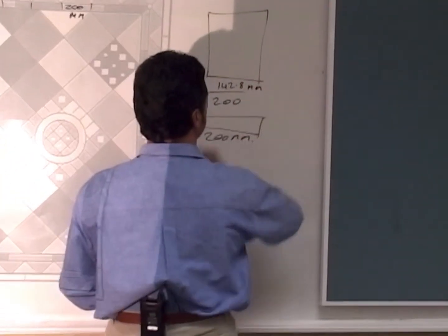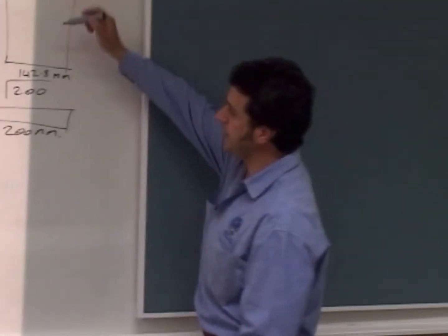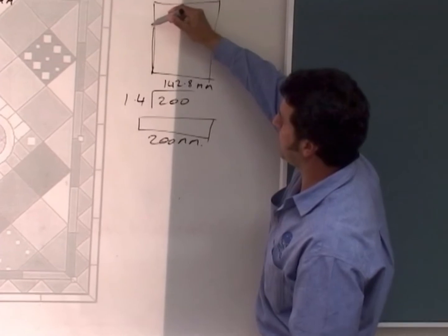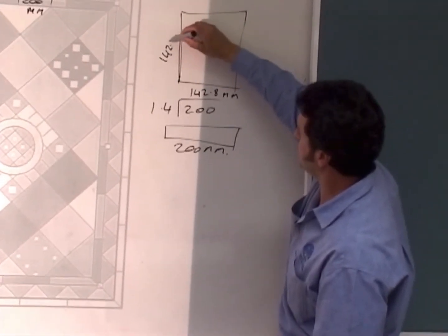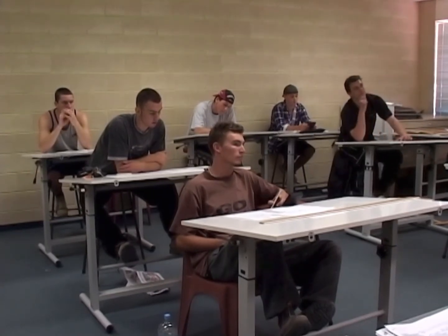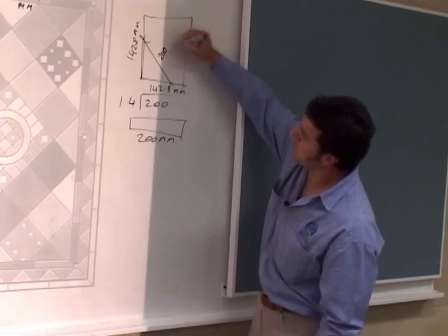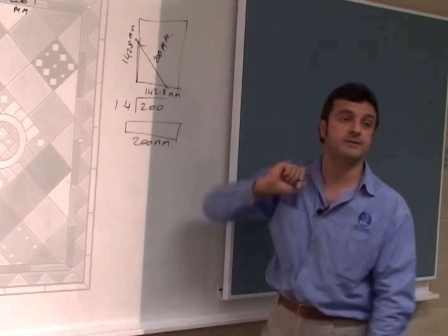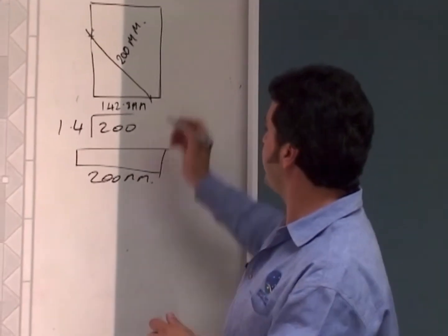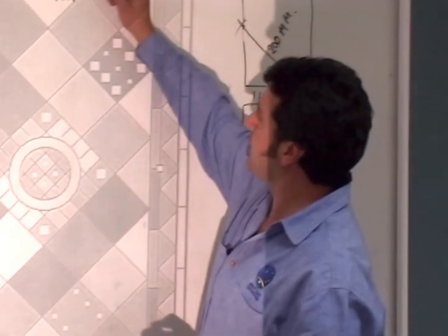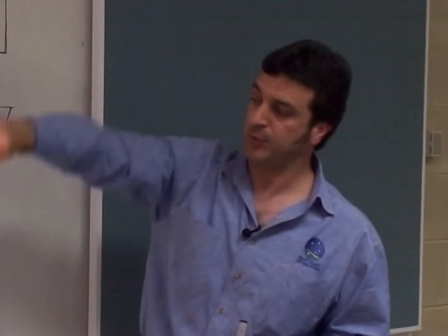So we've got 142.8 millimetres. That tells us that if we cut our tile 142.8 millimetres up the square side, and we put a diagonal cut through there, that'll give us a total span of 200 millimetres. We're going to need that 200mm span to link up with our triangles and our 50mm between the internal and external strip border, and our tessellated work will be in between that, running around all the perimeter of the work, as you can see on the board.